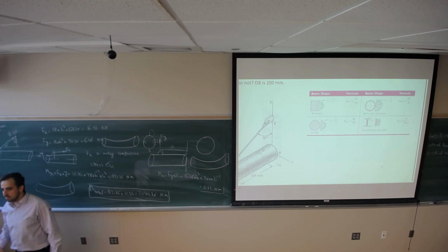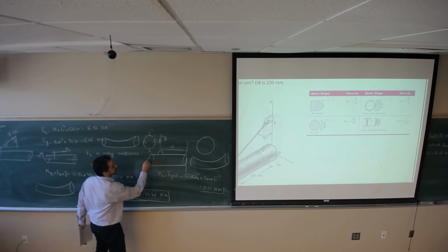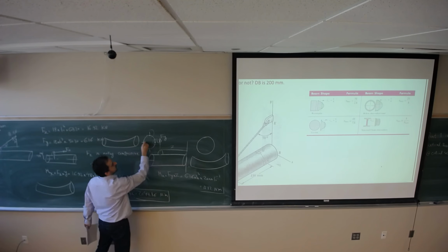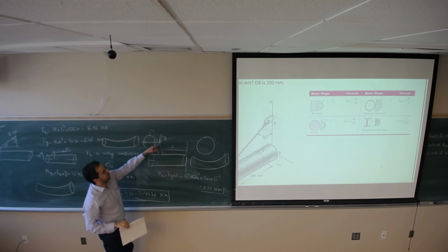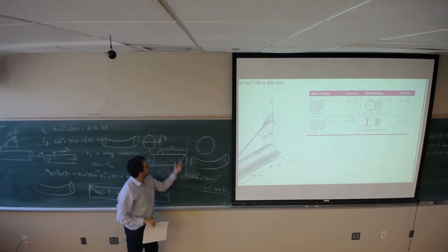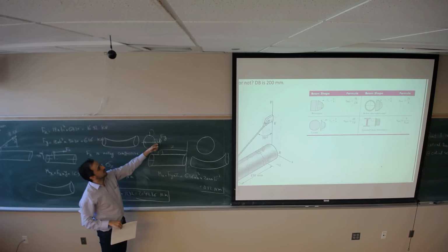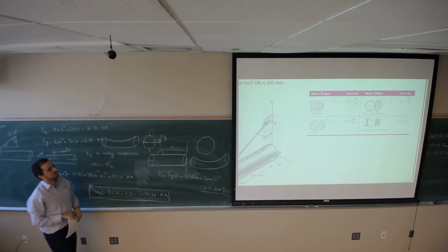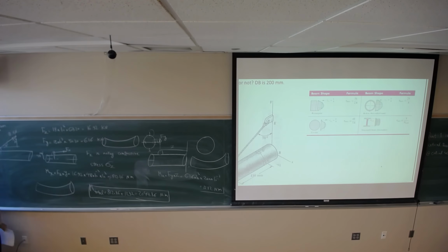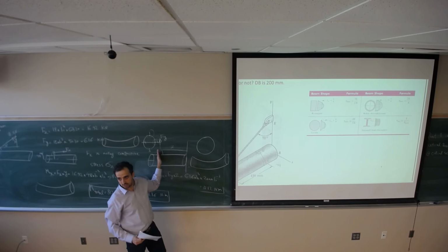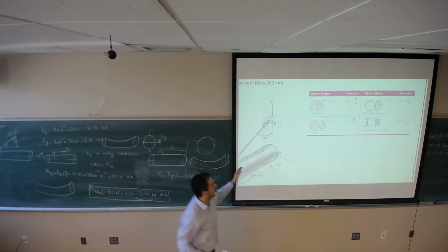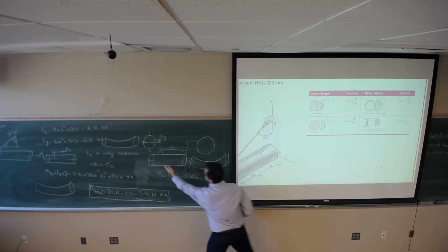Okay. So the maximum shear stress is gonna occur at this line, which is not our candidate for the bending moment. What I'm saying is, this transverse shear stress is significantly less than the normal stress that you will see on point 1. And that occurs uniformly across the pipe? Yes, because the transverse shear force is gonna be the same over the pipe from point A to B.